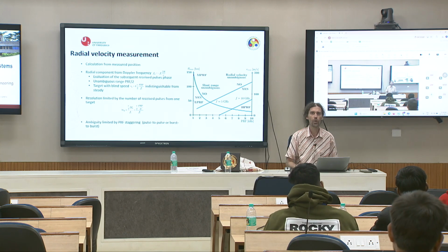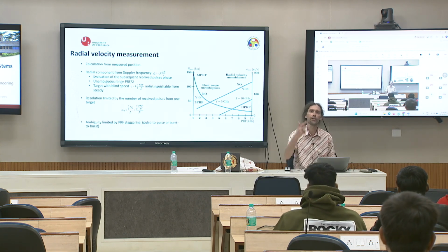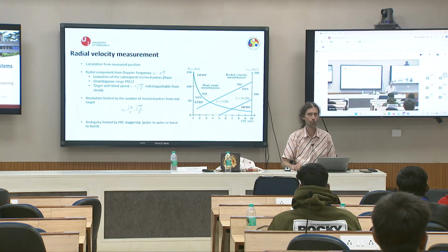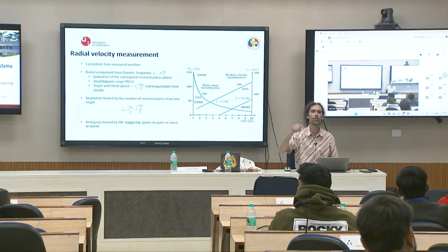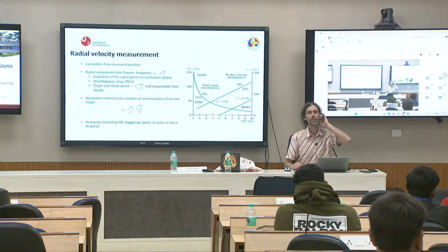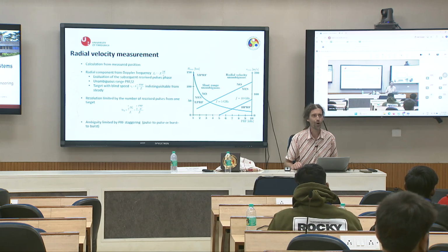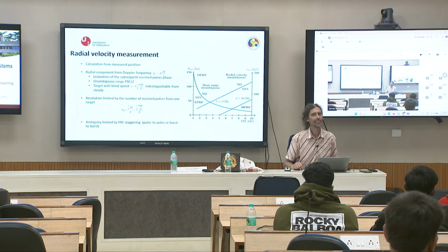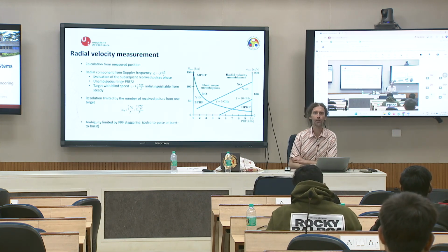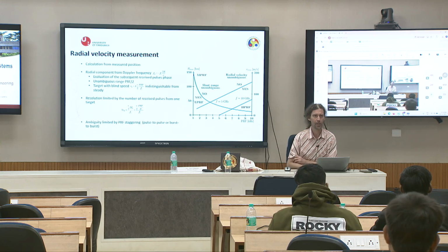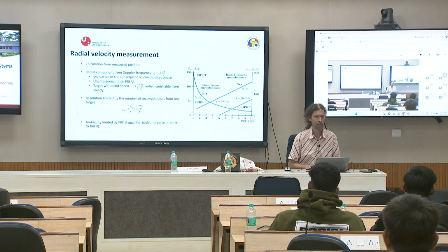And now imagine you have more targets. How can you know that these 3 ranges correspond to this one target? You don't know. How can you choose it? You don't know. It is completely independent. So you need to compute all combinations. Believe me, or I can send you some more information about this bistatic measurement, but bistatic generally is more and more complicated. It is not so easy.